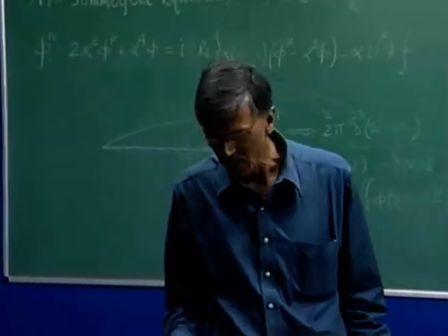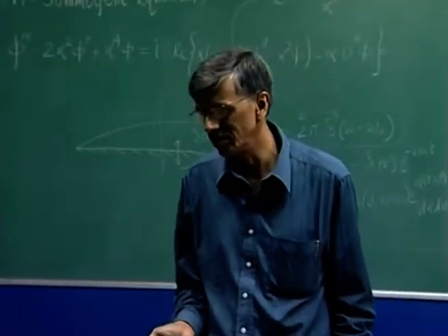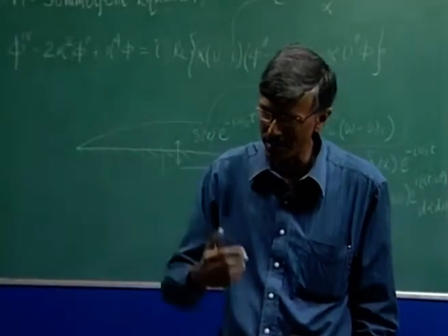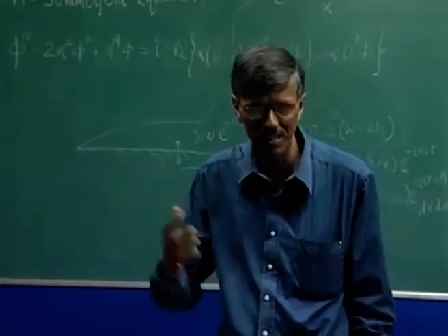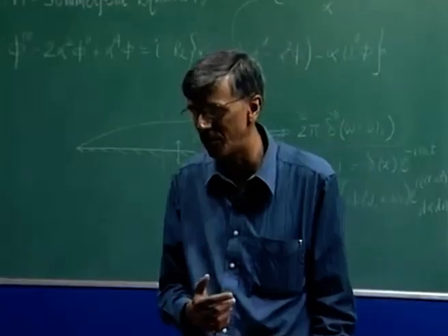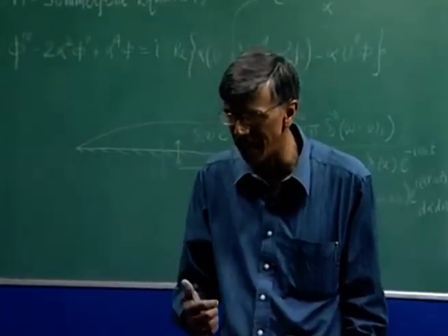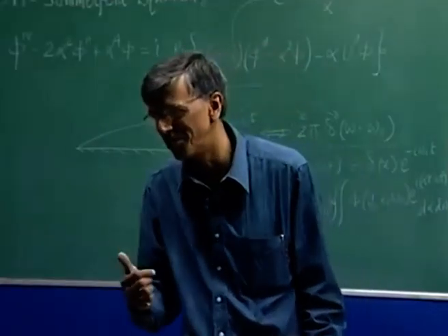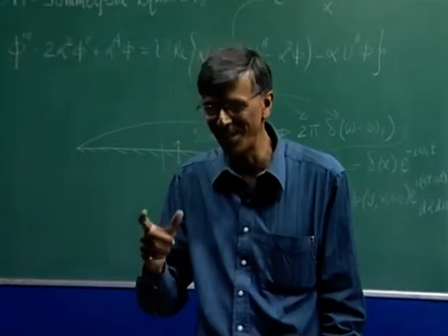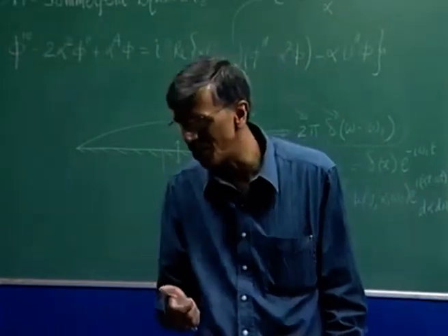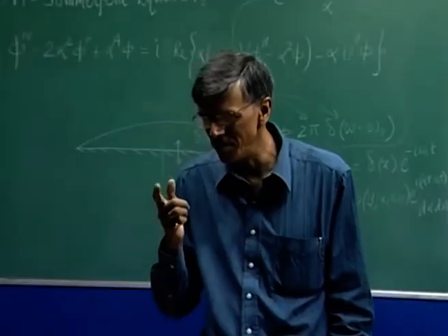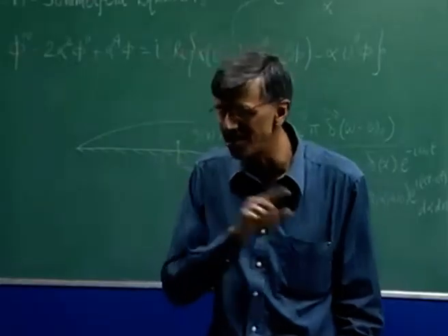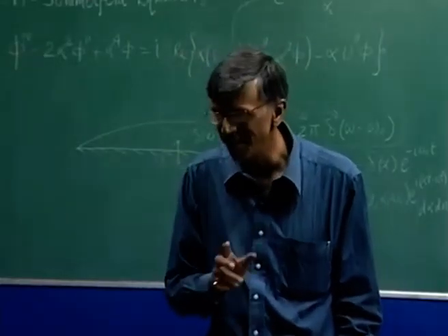For example, talk about clear air turbulence. There is a case where we have figured out that if an atmospheric convected vortex is approaching the aircraft wing, then a pilot can decide whether to go over it or below it, provided he knows the sign of the vortex. If you are talking about a vortex which is rotating counterclockwise, it would be very, very advisable for the pilot to duck under it, and then instead of destabilizing the flow, it will stabilize the flow.